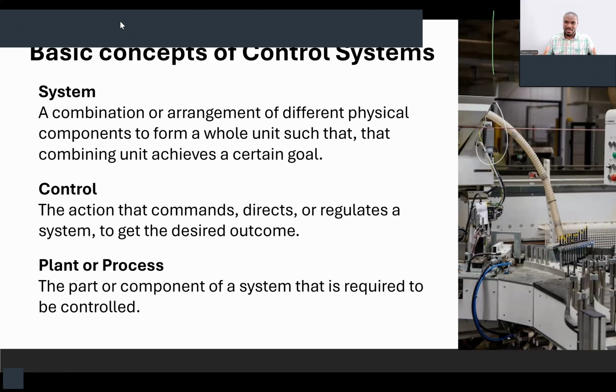That's a system that does something, that provides or distributes water, okay, into a building. It gets the water, so the water is pumped from a borehole. It stores the water in a tank, okay? But that tank does not only act as a storage system, it's also a distribution system, passive distribution. So it is elevated to some height, okay? And then that water is distributed to the various buildings. That's a system. Physical components have been arranged, they've been combined in a certain way.